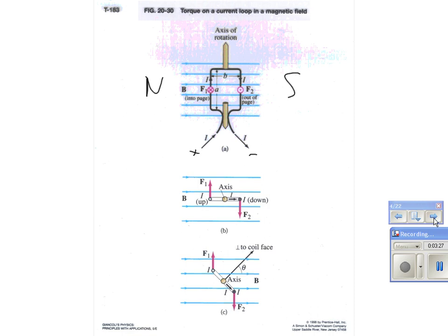And this side, see, here's positive, here's negative. So here the current's going up, and on the right-hand side it's coming down. So just like before, this thing's going to want to rotate. And it will rotate until this end of the loop is at the top, and this end of the loop is at the bottom. You with me? Good so far? Now, if I had a way at that very moment to flip the current so that in this end of the loop it was now going in, and in this end of the loop it was coming out, it would rotate.